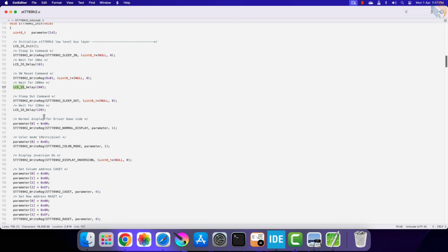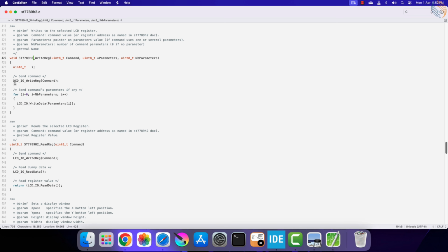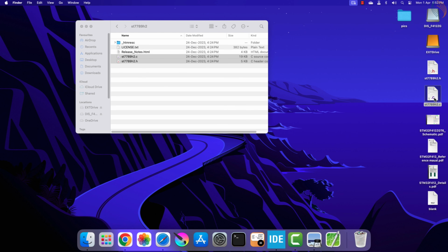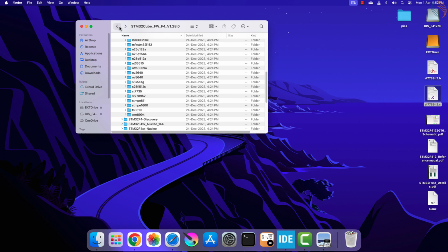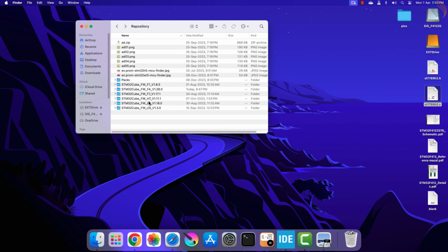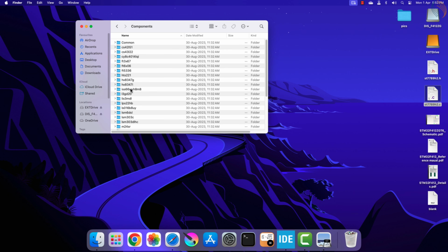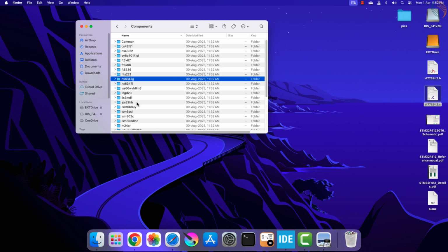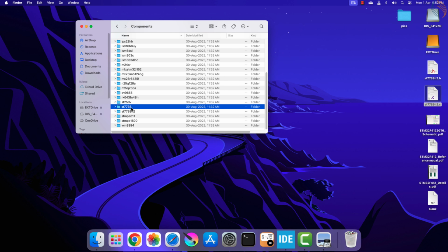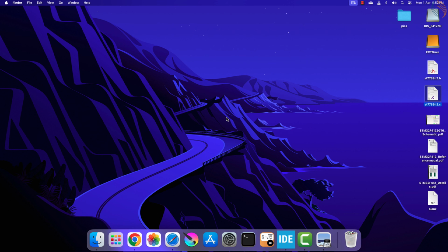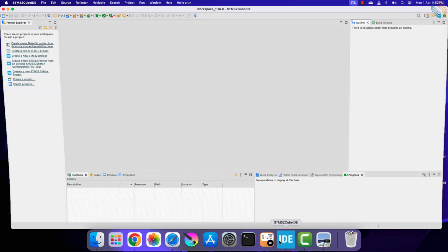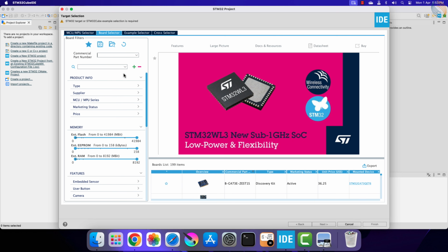These I/O functions connect the library to the display. You can see we have the I/O function for initialization, and another one for delay. We also have the function to write the LCD register. Basically we just need to define these I/O functions in a separate file, and use the appropriate method to send the command and data to the display. The method depends on how the LCD is connected to the MCU. We can use the normal GPIO operation, the FSMC, SPI, or I2C, however the display is connected. I will demonstrate this in a while.